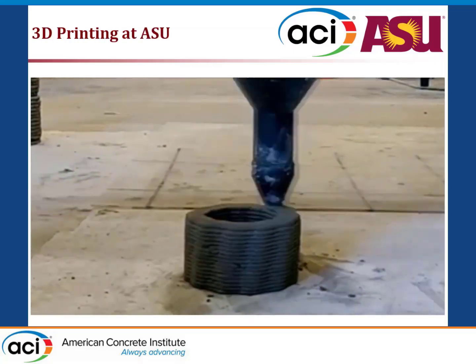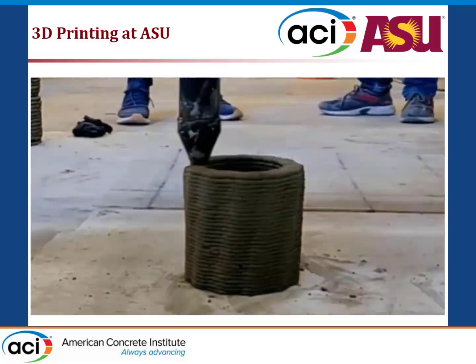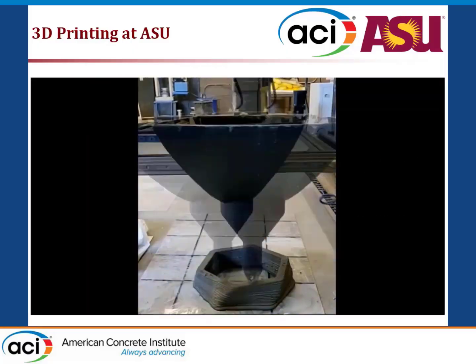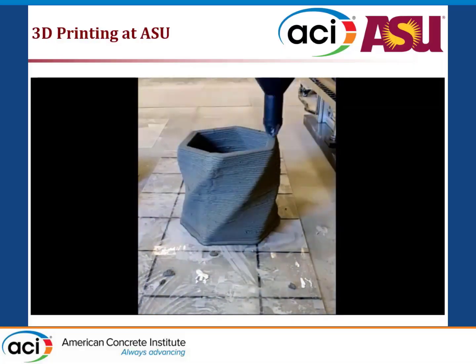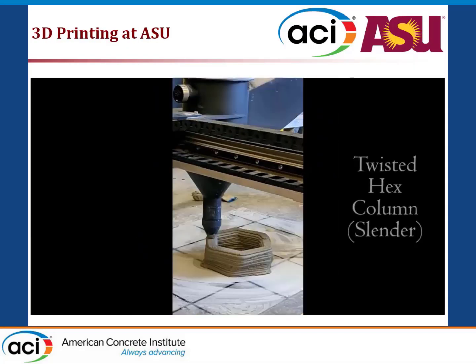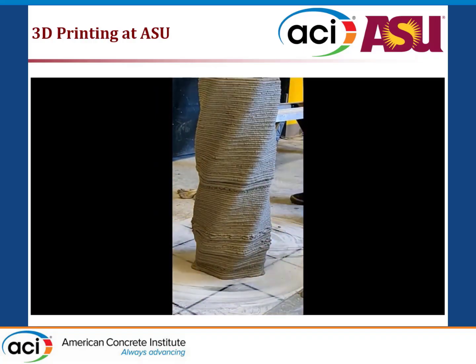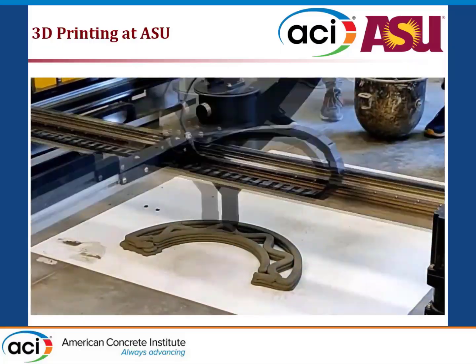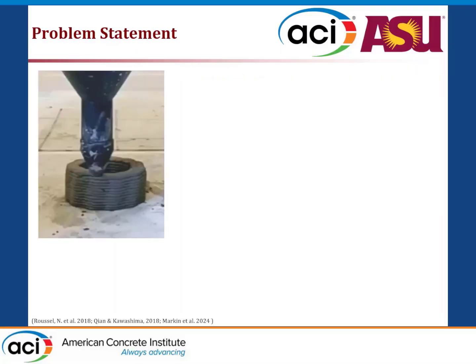So again, similar thing: 3D printing concrete, you can print without formwork, with architectural freedom. In terms of shrinkage, the most important part is that there's no formwork, so it's exposed. The high exposed surface area is the biggest problem, causing moisture to be lost from the printed system and causing it to shrink and crack. The other factor is the high binder content. So basically it gives you plastic shrinkage as well as autogenous shrinkage. Because of the absence of formwork, as I said before, there is high surface area exposure, leading to more significant moisture loss in the initial concrete mix.